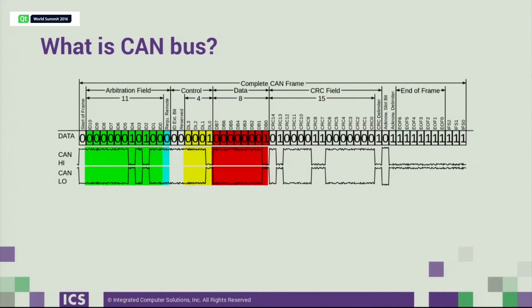So we won't get into all of the technical details of the protocol, but it's a multi-master serial bus with multiple nodes. You need at least 2 nodes on the network to communicate. And the different nodes can really vary in complexity from very simple devices to more complex things like host computers. There's even possibility for things like gateways to other protocols like USB or Ethernet.